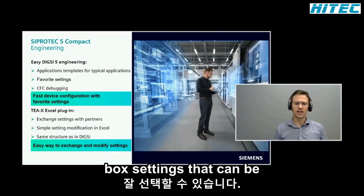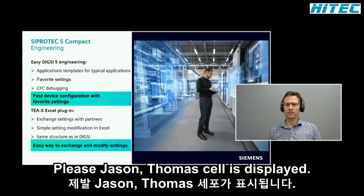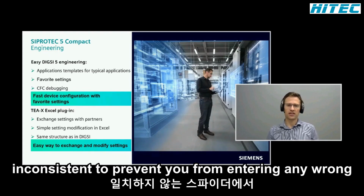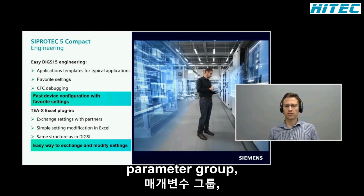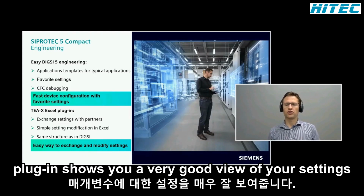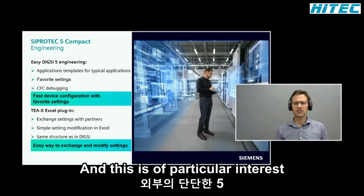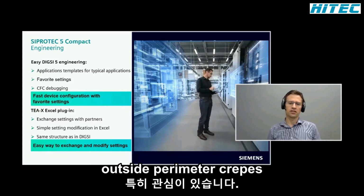Settings that can be entered as a value, for instance, a pickup of a current, adjacent to the cell is displayed the range of allowed values. Values outside of this range are displayed as inconsistent to prevent you from entering any wrong values. Now, especially if you're using more than one parameter group, the TAX Excel plugin shows you a very good overview of your settings across all the different parameter groups. And this is of particular interest because the SIPROTEC 5 Compact offers up to 8 parameter groups in the device.